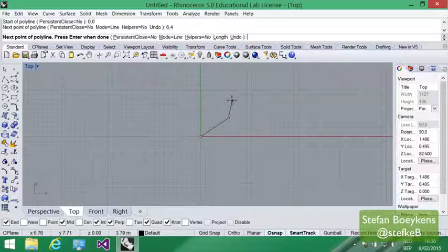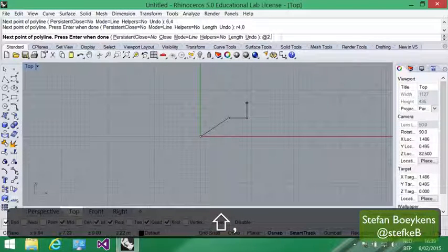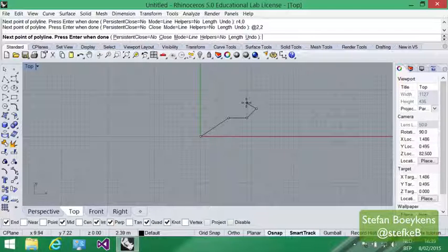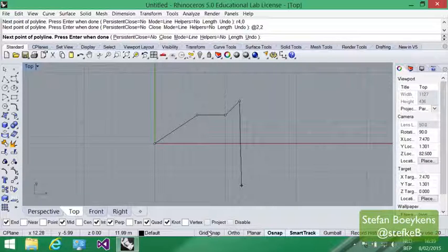It also works with relative coordinates, and relative coordinates are just like in other CAD applications, measured from the current point. We can type the R for relative, say 4 units to the right and no units to the up direction, which gives a horizontal line of 4 meters long. Or we can use the same symbol as in AutoCAD, the @ sign. Let's say 2 units to the X direction and 2 units in the Y direction. Gives you another clean position. Of course, using the grid snap, if you work in whole units, is often easier. Then you can work very intuitively.